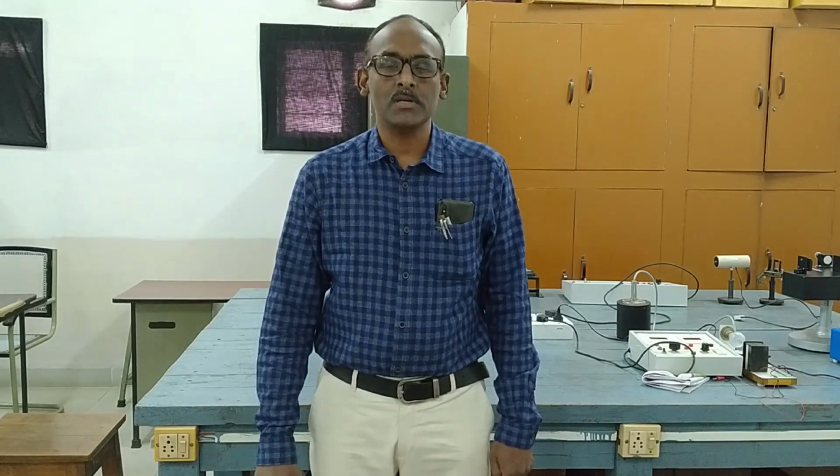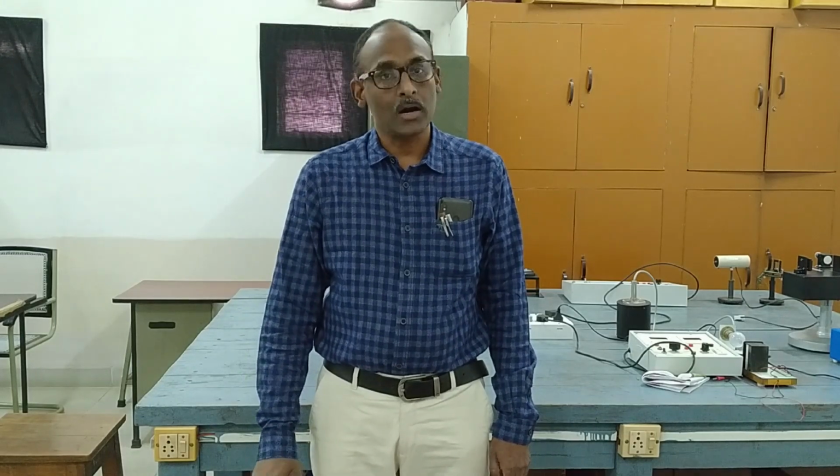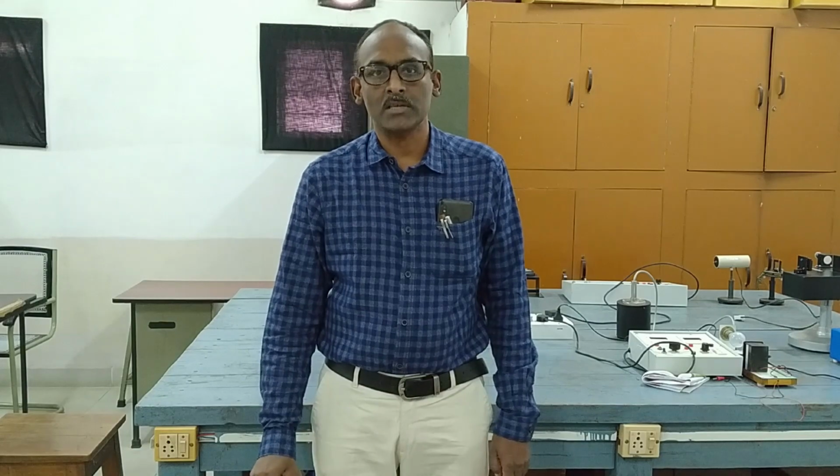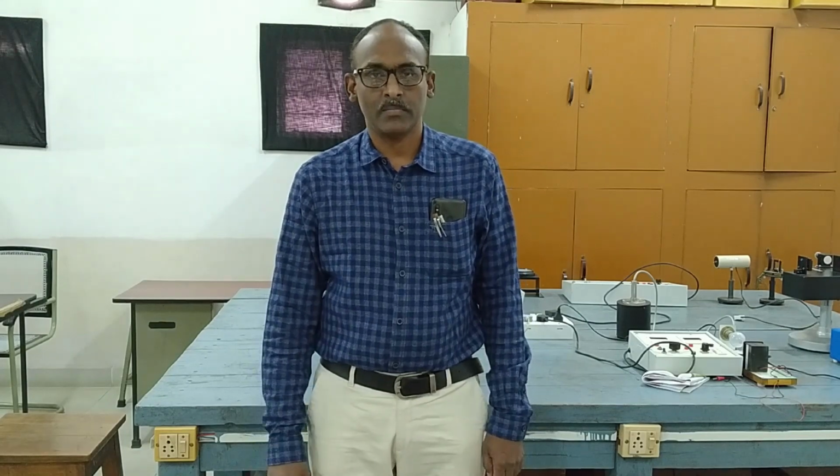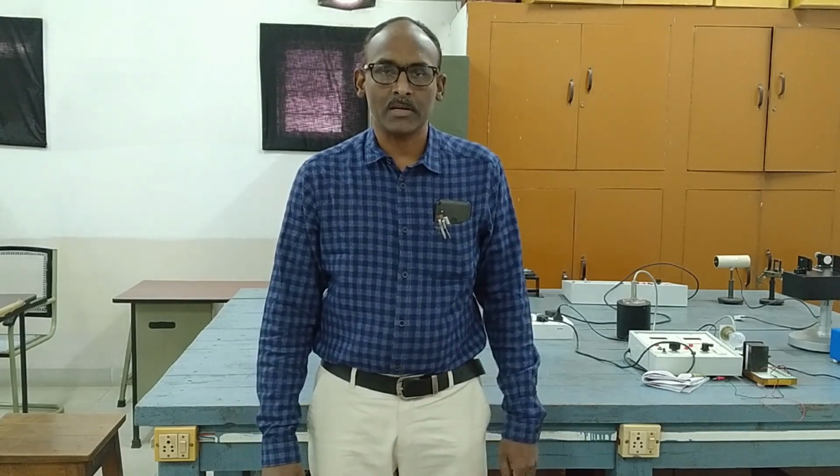The Zener diode especially is operated in reverse bias under breakdown to use it as a voltage regulator. The LED is also a P-N junction diode, heavily doped, made of large bandgap semiconductors, and it emits light in the forward bias condition. That you have also done.